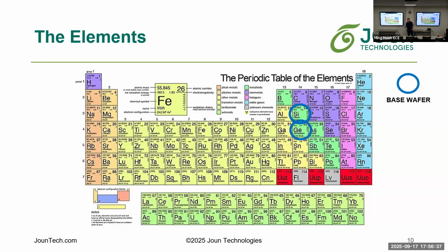We also see it combined with germanium. So you have a compound wafer, silicon germanium. You have silicon carbide, another emerging element used. You have gallium, that's another one that's used. And of course, gallium arsenide. And all these different combinations and compounds are used basically to achieve different things. The silicon one is what I would call the workhorse of the semiconductor industry. Most of your base logic, et cetera. Oh, by the way, if you do have a question, feel free to raise your hand.